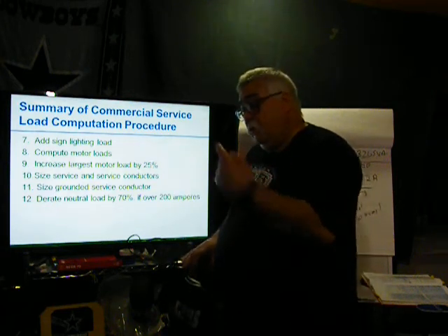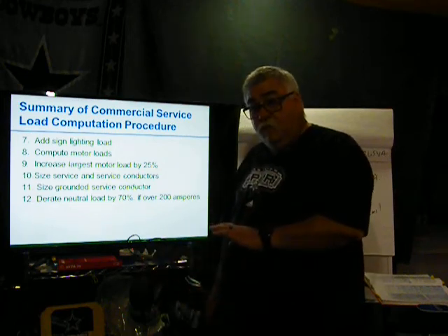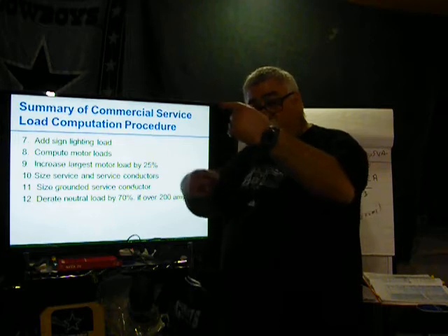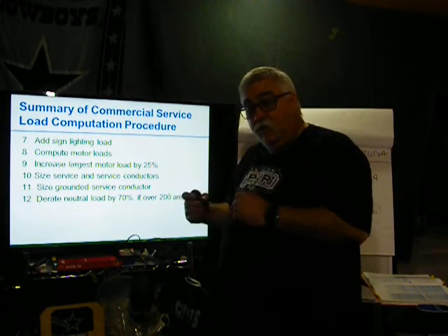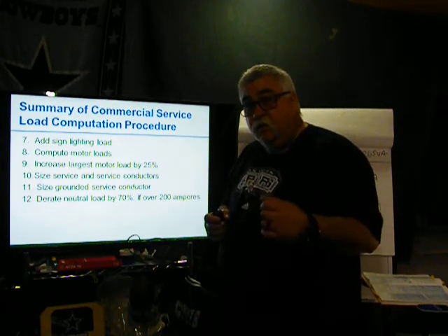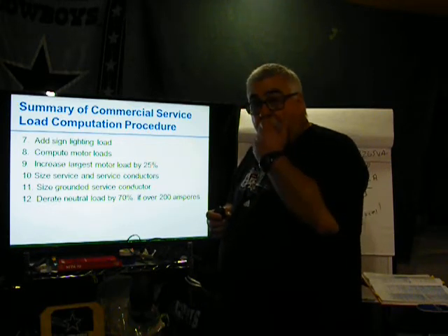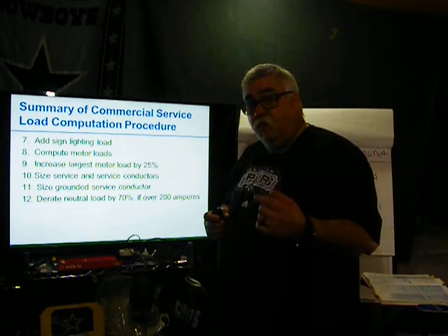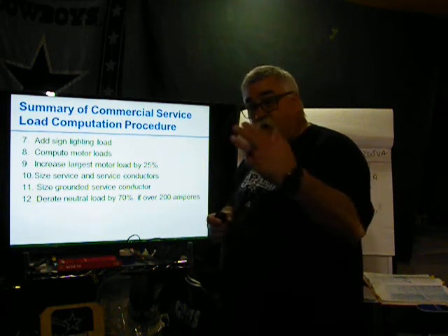Our grounding, once we get the ampacity, okay, how do we find the amps? VA, watts, divided by voltage gives us amps. So once we have the amperage, we can go to table 250.122, it's also in the uglies, and find our grounded wire, not a GEC, not a grounding electrode, but our grounding wire that's going in the conduit with our neutral and 2 hots.